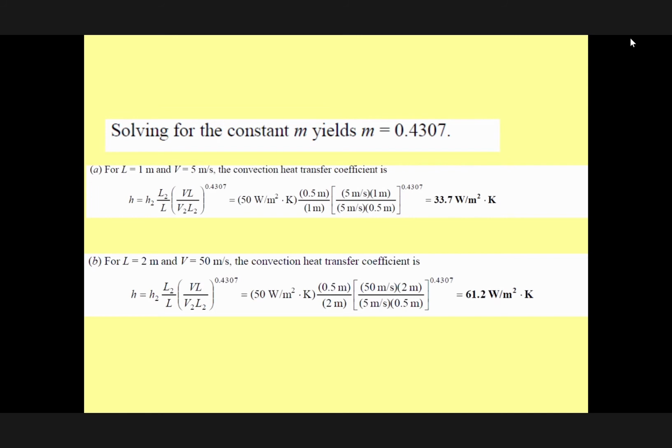But you saw it last lecture when we were dealing with flow between two plates. Between two plates, the velocity profiles merge and the velocity profile remains the same. That's why in the case of a pipe, we use a characteristic length as R, and that remains constant. Therefore, this is something that you have to slowly get a better understanding of in the convective heat transfer problem.